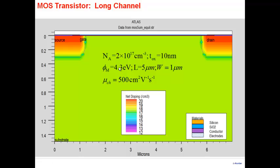For today's lecture, we'll take mostly a long channel MOSFET with a fairly long channel here, 5 micron. The width, because it's a two-dimensional simulator, by default is kept equal to 1 micron. But for any other width, all you have to do is multiply by that value. So whatever the width, if it's 10 micron, whatever current you get, you multiply by 10.